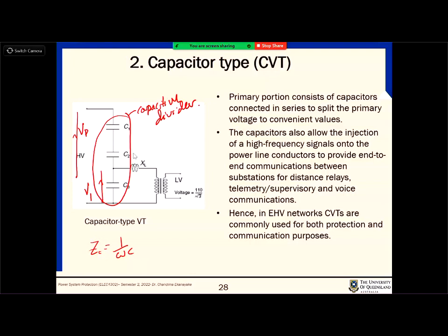Now the 50 Hertz or other lower frequencies, it is blocked. But for that particular frequency, you can create a resonance using this system, right? So if you feed that signal to this system, then you can send that signal through the same wire without disturbing the normal power. And then we can filter it out because for that particular frequency, this capacitor impedance is smaller.